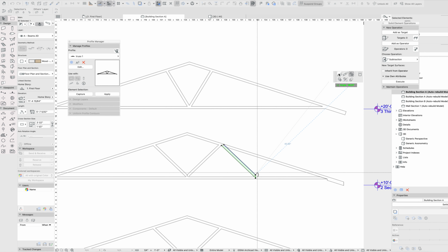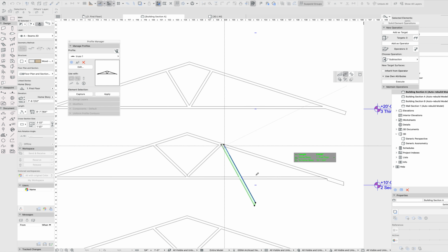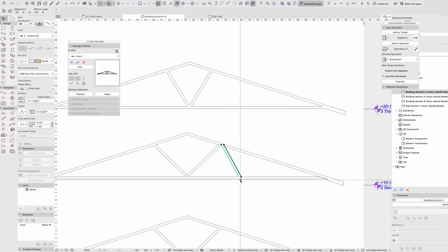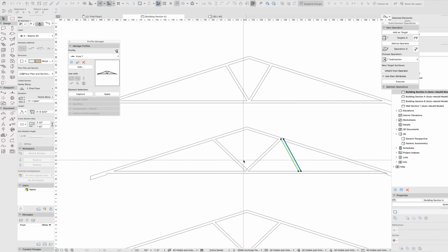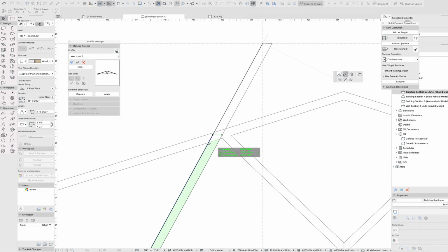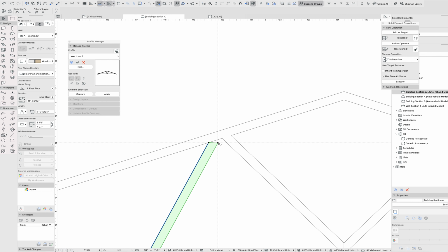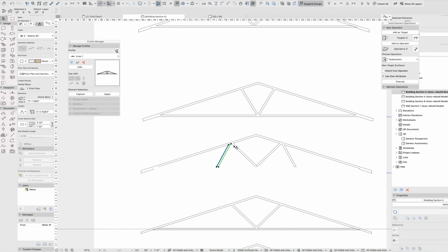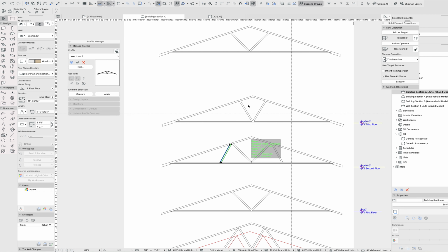Again, using the pet palette, I can change the slope, change the extrusion, change the angle of all of these connections. So using beams, you can actually sort of almost on the fly model these up. If you have one beam working in your plan view, you can start adding and copying and mirroring and rotating, or not really rotating, but anyway, you get the idea. You can start building these trusses out in a section view directly. And if you underlay the shop drawings, you can get those lined up perfectly.